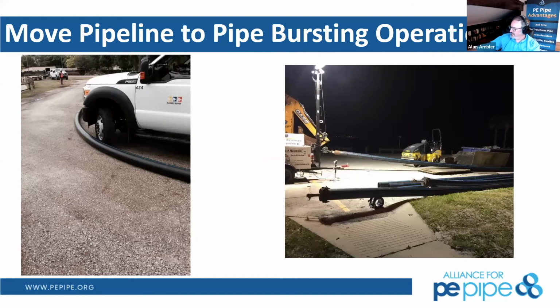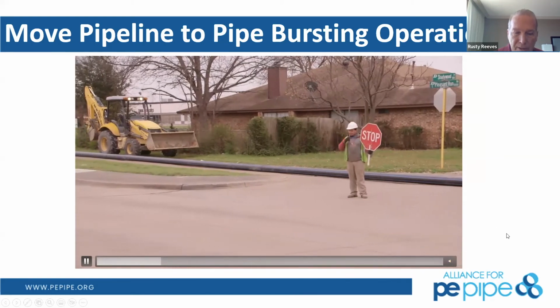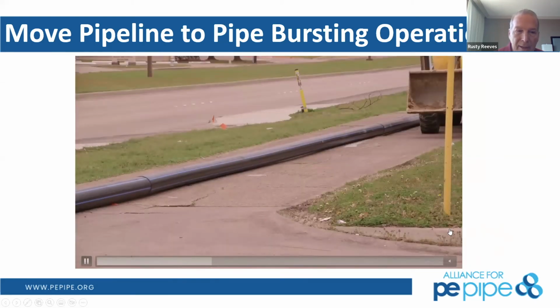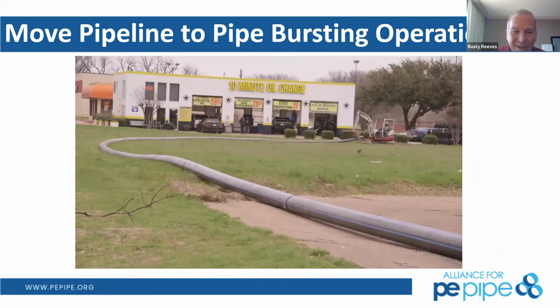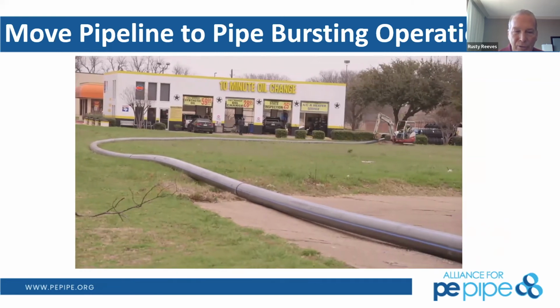Rusty, yes, that's exactly what I was about to talk about. One of the great characteristics of polyethylene is that abrasion resistance. If you notice, a lot of the snow plows in the northern states use polyethylene on the base of those to keep from tearing up the roads, but it's still a very, very durable product. But as you said, you can damage it. A tooth of a backhoe, something like that, can definitely do some damage.